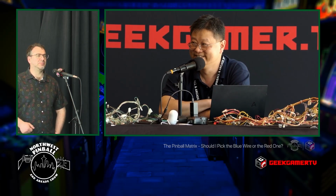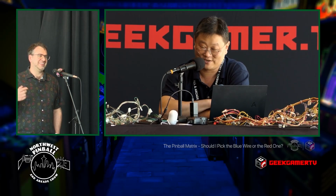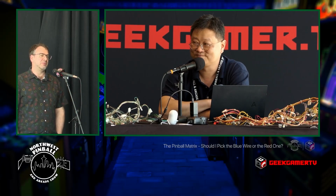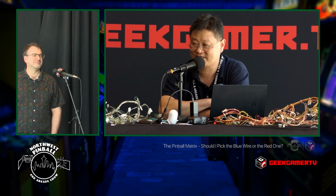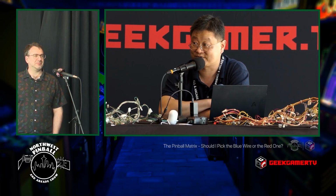Thanks. And by the way, to your point about diodes, I did have a diode problem in a game I was working on. It wasn't installed. Okay, that's another case. Some lights that were not supposed to be on were on at the same time. Yeah, that's the backflow of current, but that's beyond the scope of what I wanted to talk about. But again, that comes back to the point: a diode is required for everything that's on a matrix, regardless of switch or lamp.